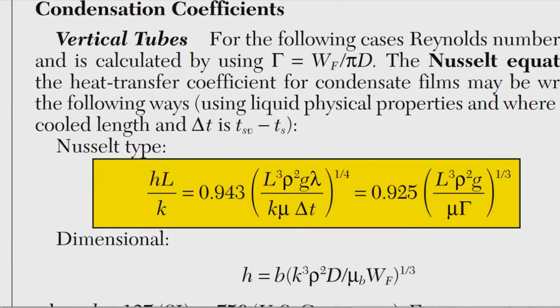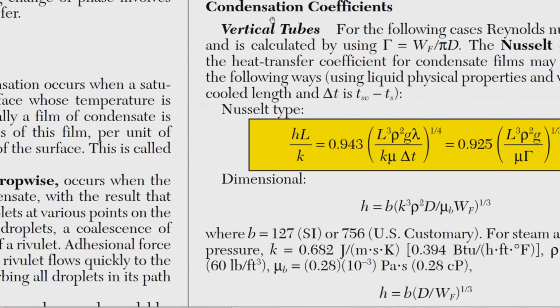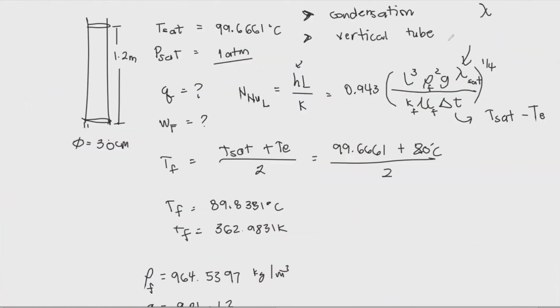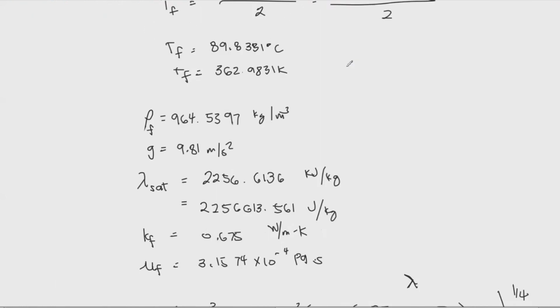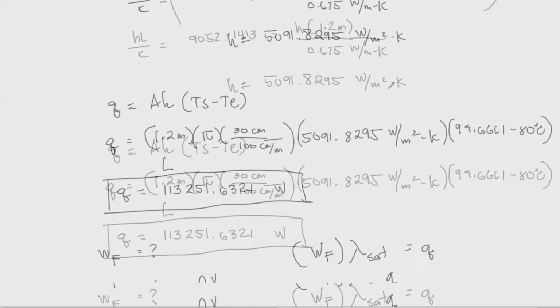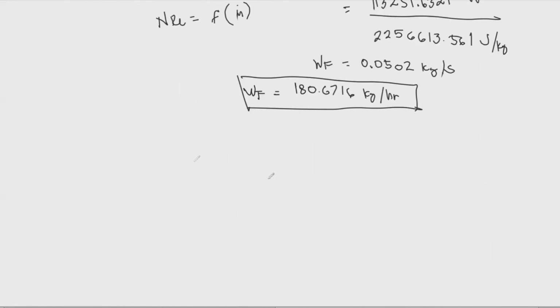It means that the flow should be laminar, and if the flow is not laminar, then we shouldn't be using this formula. And actually we have assumed that this is laminar flow, so that's one of our assumptions that I forgot to mention, because actually the Perry's handbook doesn't give you any equation for turbulence, so that's all we can do. We can assume that this is laminar. And we need to check if we really do have some kind of laminar flow.